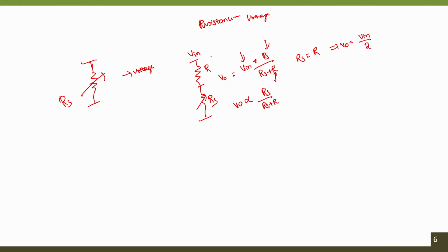So this R not only helps to convert the resistance change offered by the sensor to a voltage, it can also be used as a current limiting circuit or a protection circuit for your sensor too. Both requirements, avoiding operation at higher currents as well as converting resistance to voltage, a simple resistor can help you do.